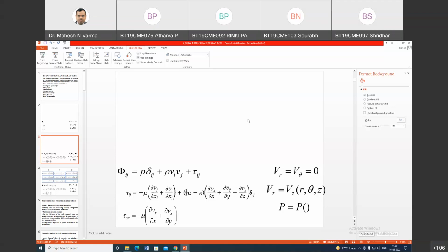What is the reason? You gave a logical reason that Vz is not a function of theta because the problem is symmetric around theta. If I move in the theta direction, all molecules experience the same forces, hence there is no driving force to change Vz. Give the same answer for the z direction.